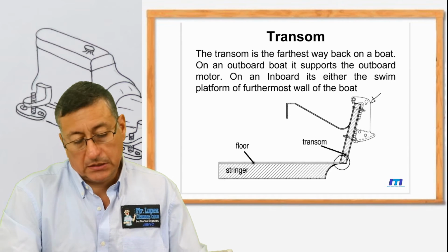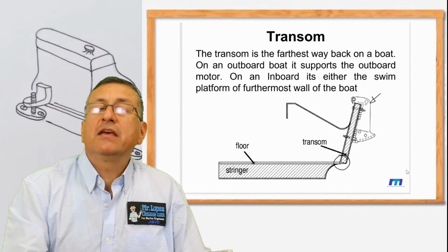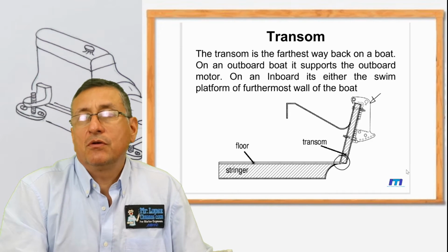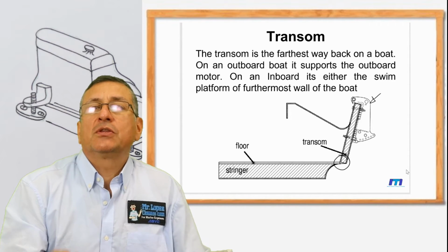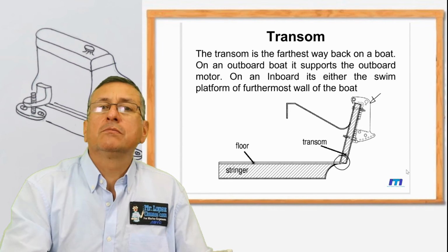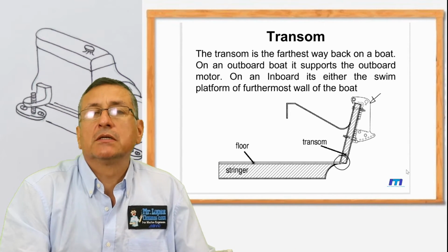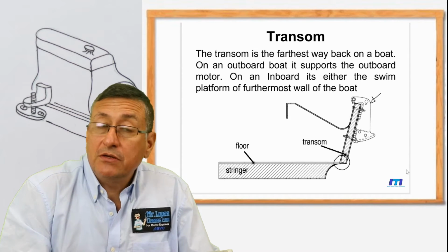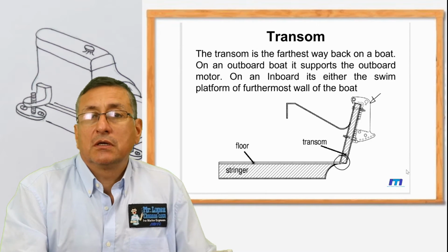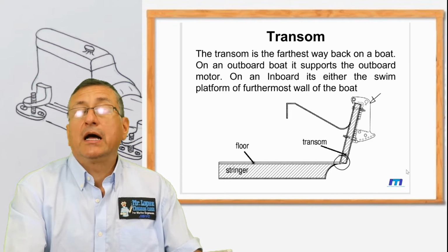But I recommend reinforcing the transom with aluminum brackets if the transom is in good condition. Don't try to reinforce the transom with aluminum or stainless steel brackets in order to cover internal problems of the transom. I recommend repairing the transom, building a new one, and additionally reinforcing it with metals, aluminum or steel. In some cases, it's a good idea to embed the aluminum inside of the sandwich, and after that the transom will be completely rigid. Yes, I love it.